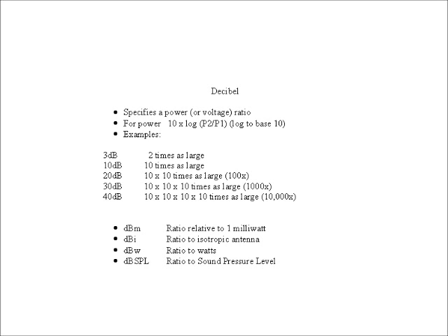But say, for example, you have an antenna where you manipulated the pattern, so it has what they call 10 dB of gain. 10 dB of gain means it's 10 times as strong as it was before. The energy directed in one specific direction is 10 times as strong as it was before.